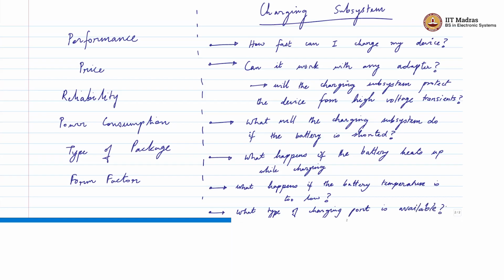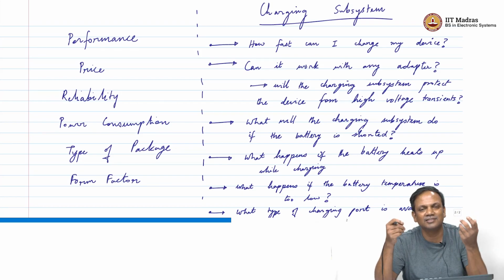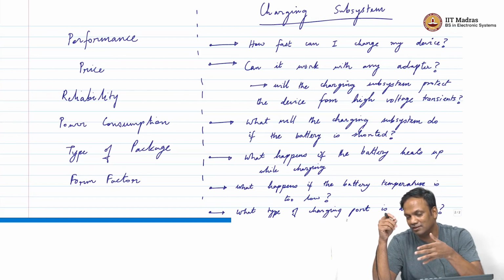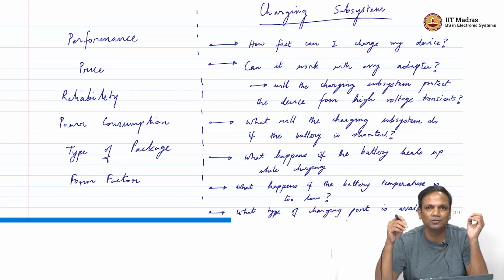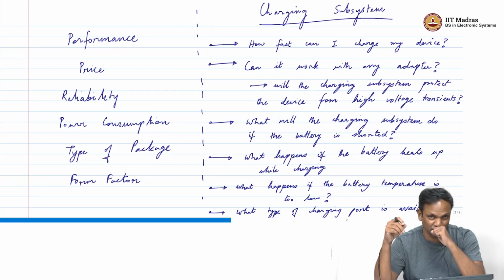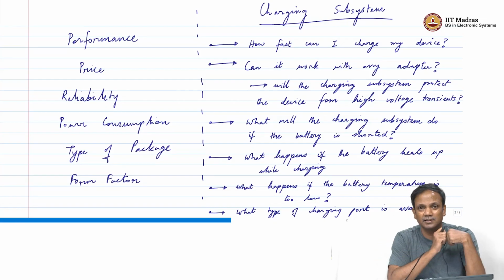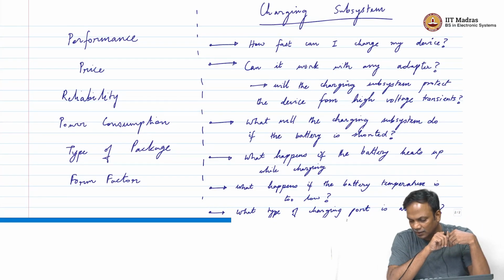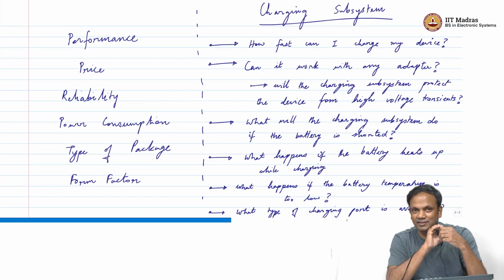We talked about the point that the embedded system designer's responsibility is chip selection, integrating those chips into hardware and software. Part of that is also decisions on type of connectors. So, for example, you might say, okay, I am going to use a USB-C connector because USB-C is the most prevalent standard today for charging. Most charging cables come with USB-C. So, that is what I am going to do. That type of decision is there for the embedded engineer to make. So, we will list it here.